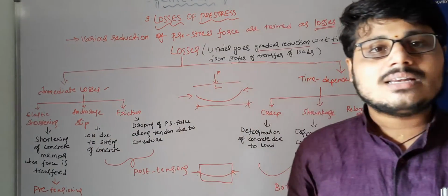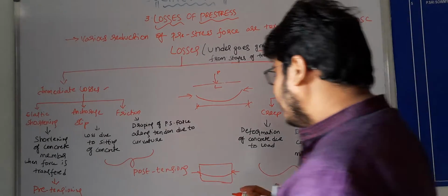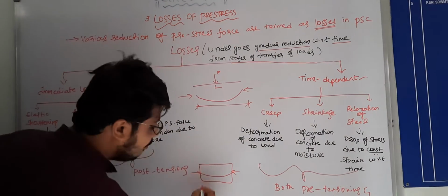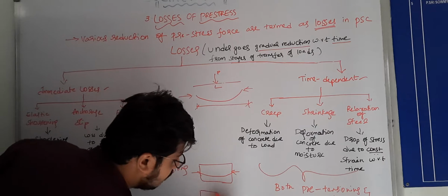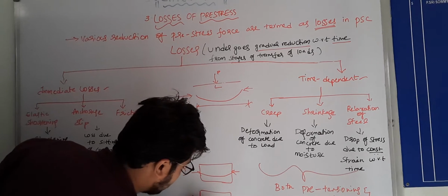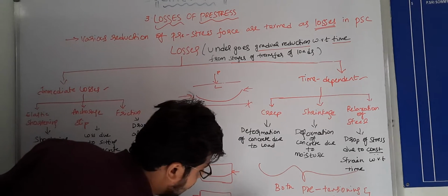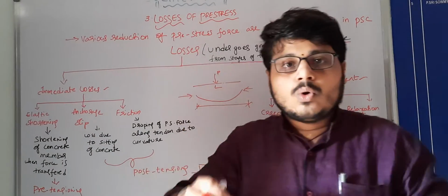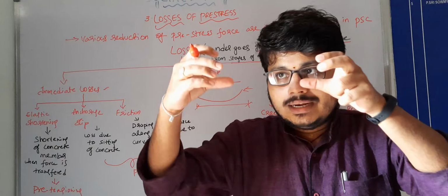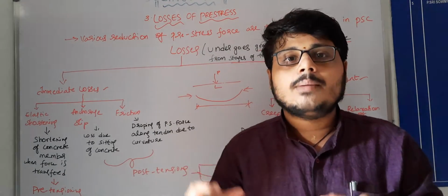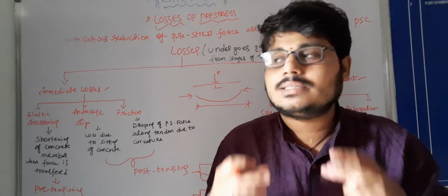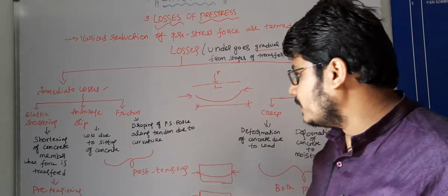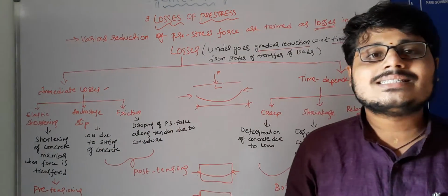Next one, anchorage slip. As we know, the pre-stressed concrete is held in the anchorage by the jacks. While setting or placing the concrete, there may be immediate losses. That is called anchorage slip.